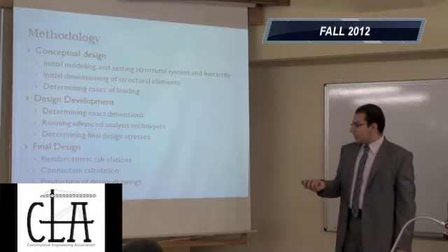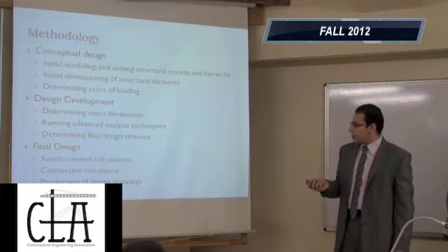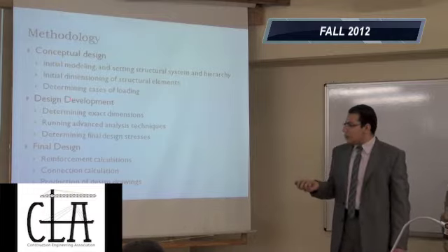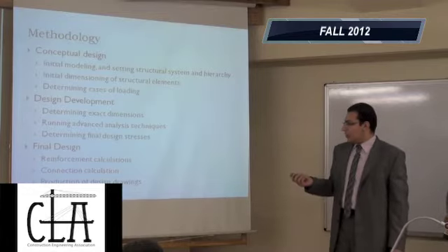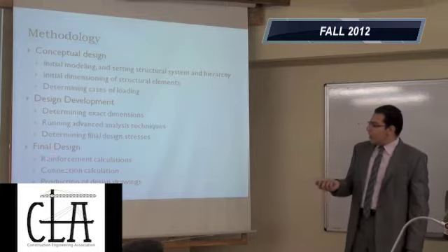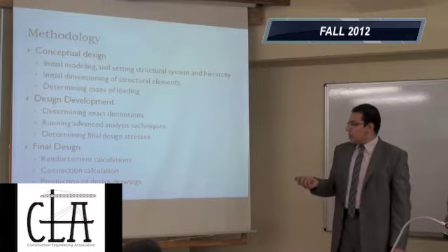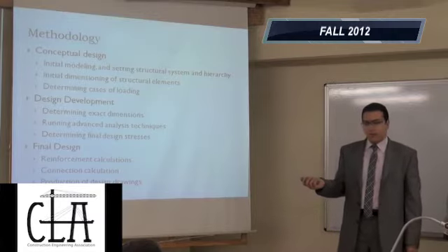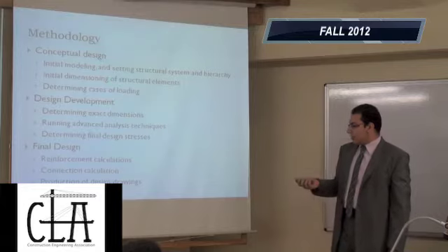In the final design phase, we are going to use all that we have done in the two other phases and decide the reinforcement, the steel grade, maybe the welding type or of the steel sections, if any. And then we are going to proceed to the connections calculations, in which we are going to take care of the anchorage, the bearing, and all of these concerns. And finally, we're going to produce the design drawings.